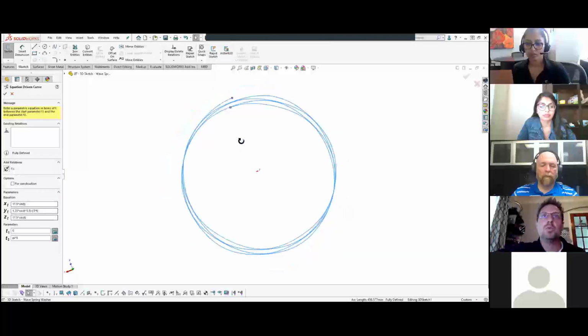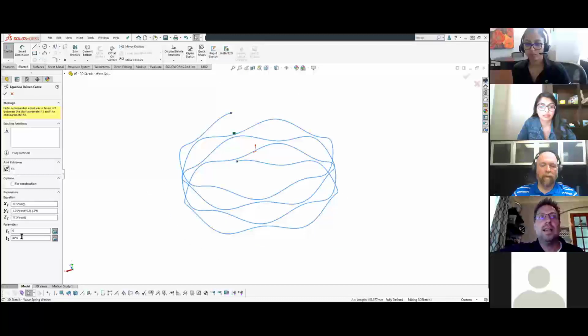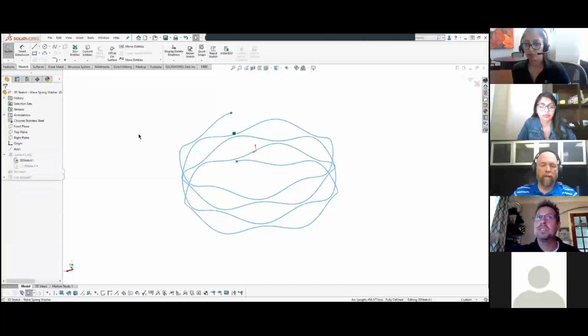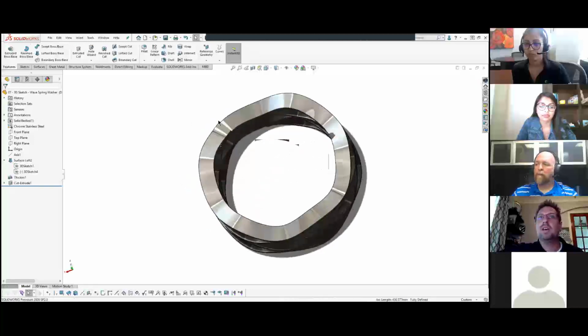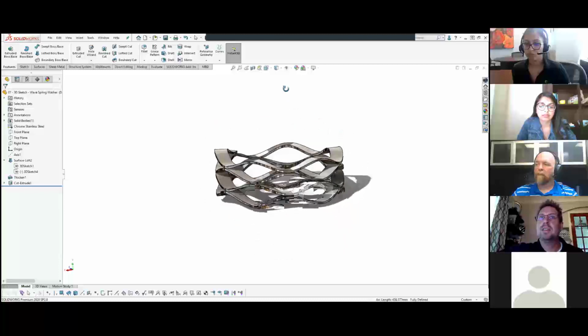And then I've got it to where it's actually changing, as I'm changing t, 0 to pi, I'm actually changing about the x, the y, and the z. And so you have what the equations are to create the polynomials, you can create some pretty awesome stuff. So create 2 of those things with a loft between them, and then I just thickened them, and then I did a little cut to make sure I was on the outside edge of that. So pretty crazy 3D sketch stuff.